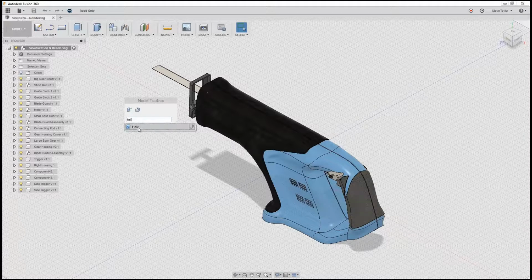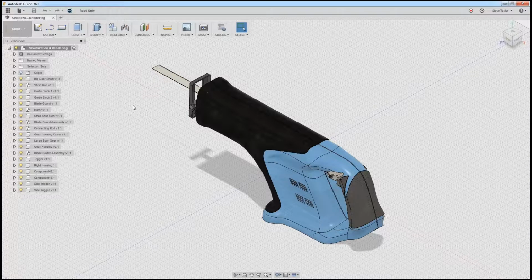Now whilst I can click on that there, if there is an arrow up icon at the side, if I click on that, it will add it to this shortcut toolbar. And if I don't want it in that shortcut toolbar, so again, S displays it. If I click and drag, I can just drag it off. So again, if I didn't want that fillet on there, click on it, drag it off the toolbar, and it removes it from the toolbar. So to add it on, it's the up arrow. To remove it, just drag it off that toolbar.